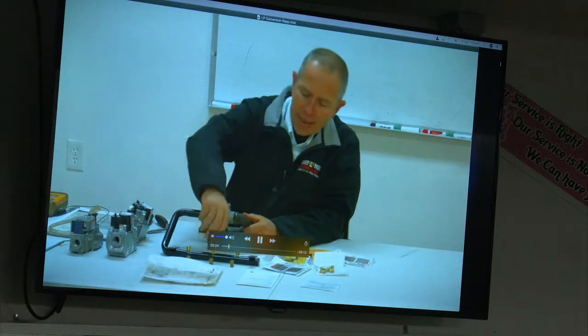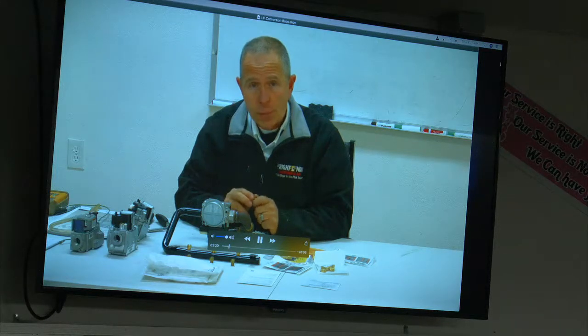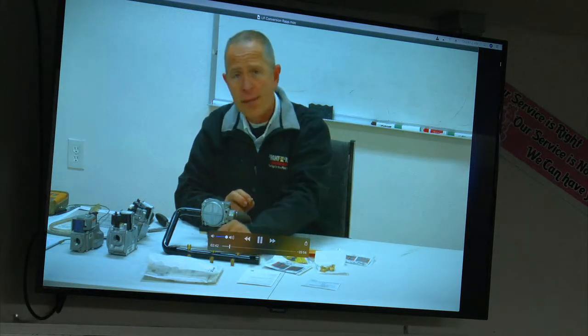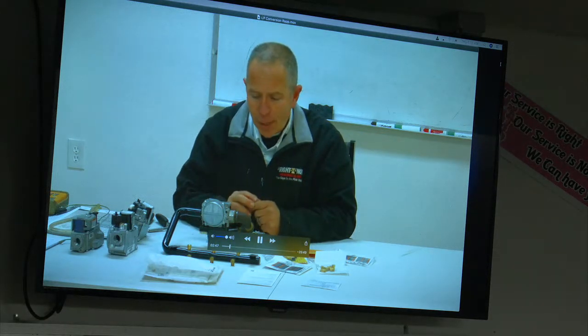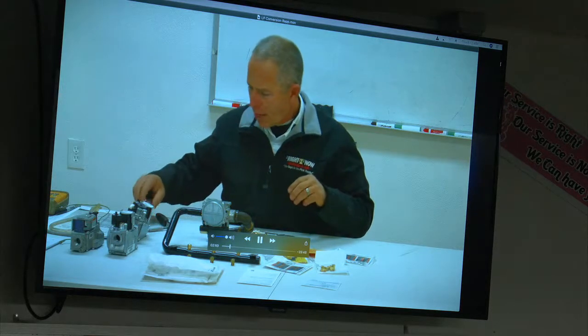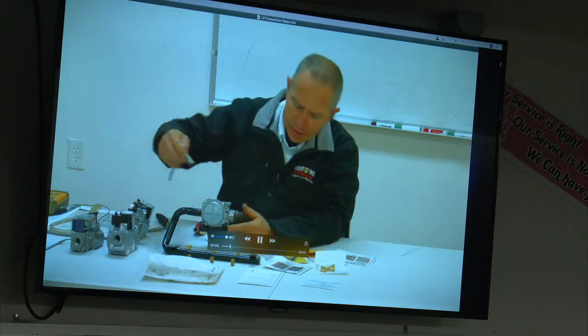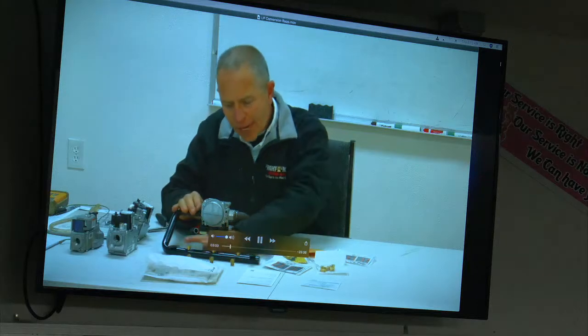And then when you're tightening them down, you use no Teflon, no pipe dope. The brass is designed to seal, so you will tighten them down a little past snug. Try to make sure that they are all even with each other, so you don't have one super wrenched and then the next one really loose. Try to keep them all at the same measurement. And you have different tools you can tighten them down with, or a ratchet. Either way, we want them nice and snug and the same height.